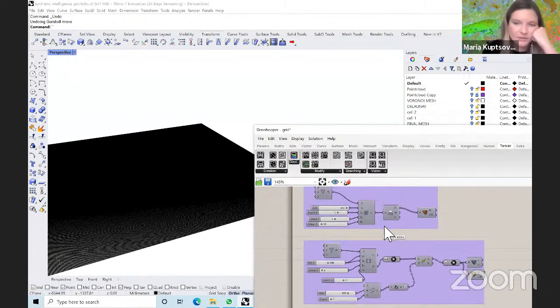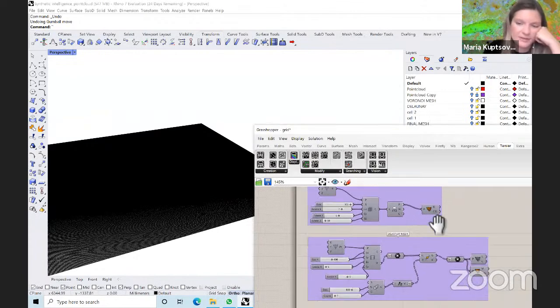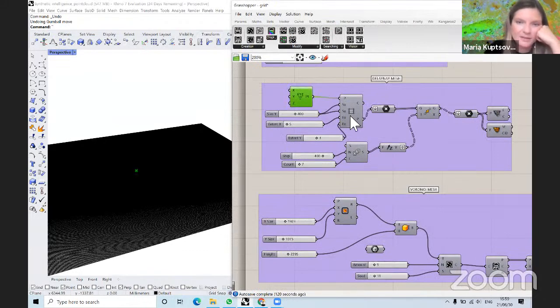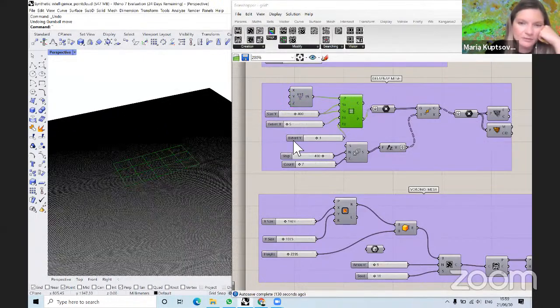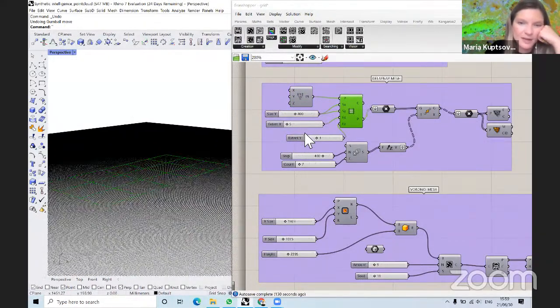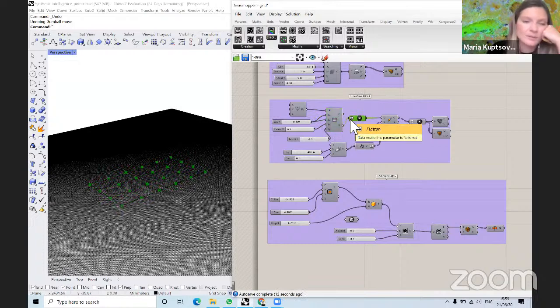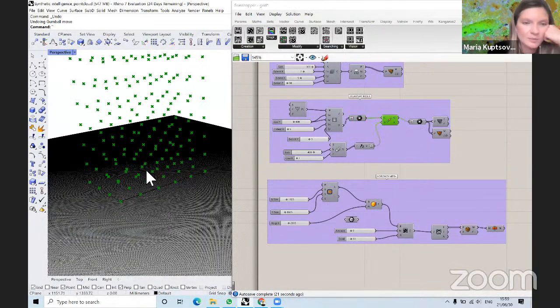And you could do different steps. I showed you a more manual scenario where you have a point, you first create a grid on the floor with these parameters of the X, Y, and a cell. So you're just adapting it to the size of your grid. So then you take these points. It's important that you're flattening it, that you have a solid list that you could be working further on, and you move them up. So basically these points are doubled up.